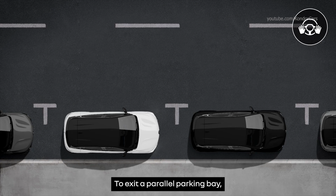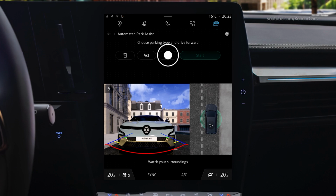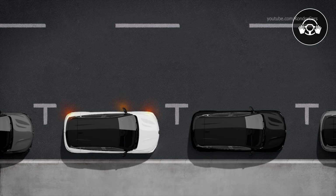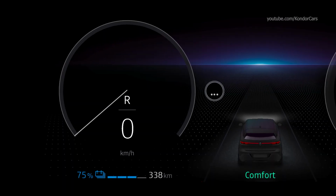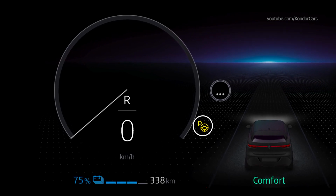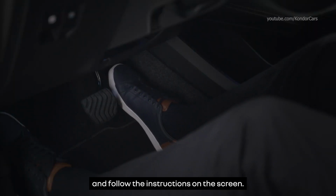To exit a parallel parking bay, select the appropriate graphic on the screen and operate the indicator light on the side you want the vehicle to exit. Stop the vehicle and press the start button. This light will appear on the instrument panel, accompanied by an audible signal to indicate the start of the maneuver. You should then let go of the steering wheel, depress the accelerator pedal slightly, and follow the instructions on the screen.